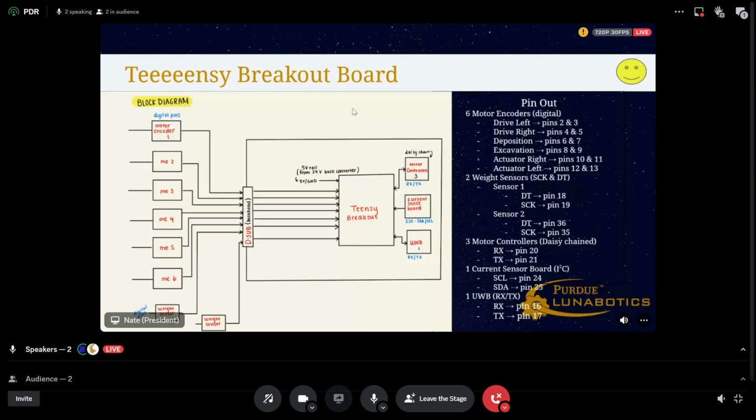Yeah, and going a little bit more into that, our encoders output 4 signals, just A, B, and then their complementary signals, A naught, B naught. So we're planning to send those signals through RS422-like protocol receivers because they're differential, and then connect them directly to the breakout board. Other than that, we have to step down the motor encoders, probably using voltage dividers to do that. Yeah, so I think that's pretty much it.